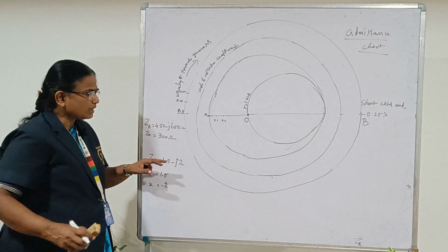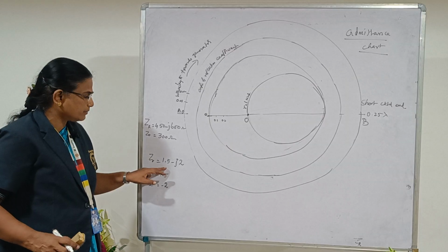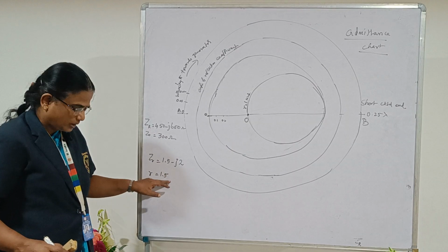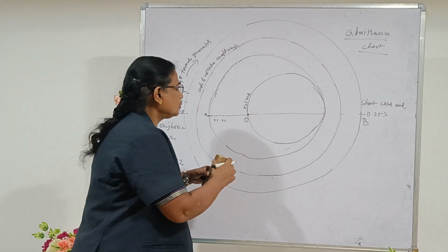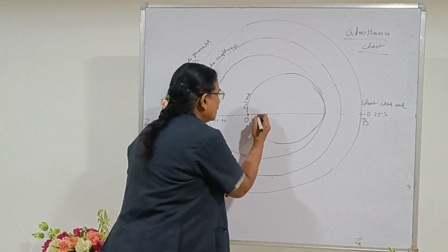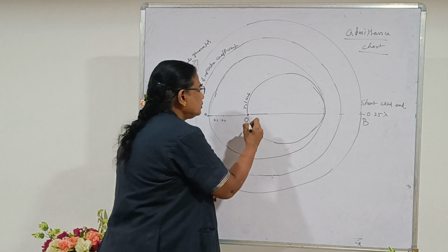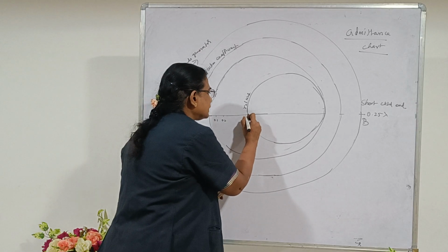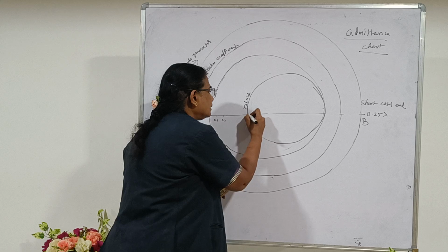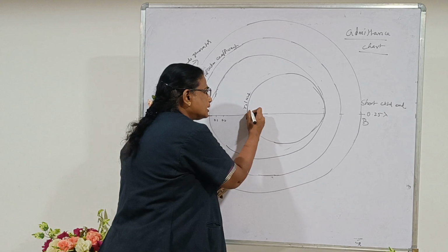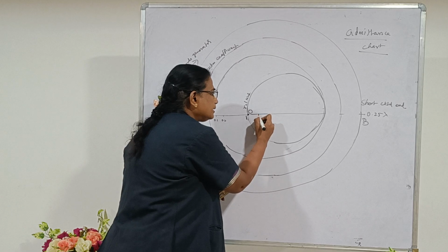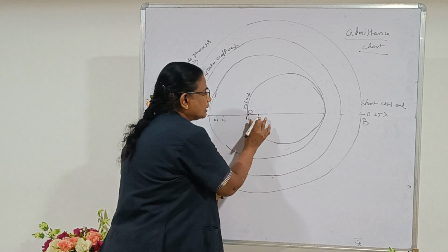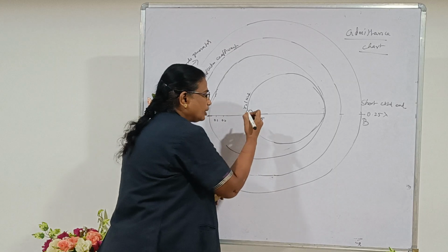So we have the R circle. First, you locate the R equal to 1.5 circle. Along the horizontal axis you can see the value for R. R equal to 1 circle passes through the center. So it is the 1 circle. We have already marked the center of the chart as O, and then you locate that 1.5 circle. Let me write, this is the 1.5 circle located.